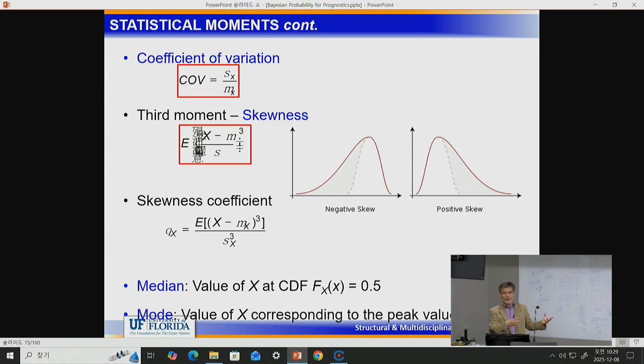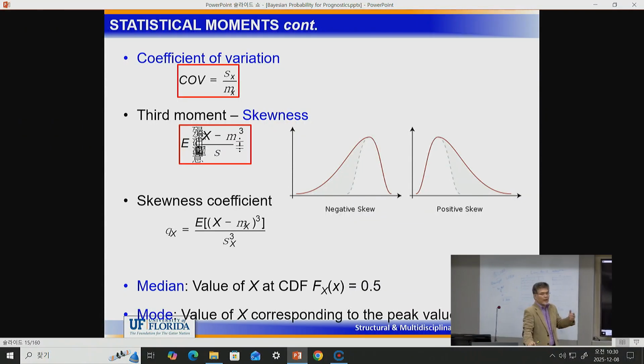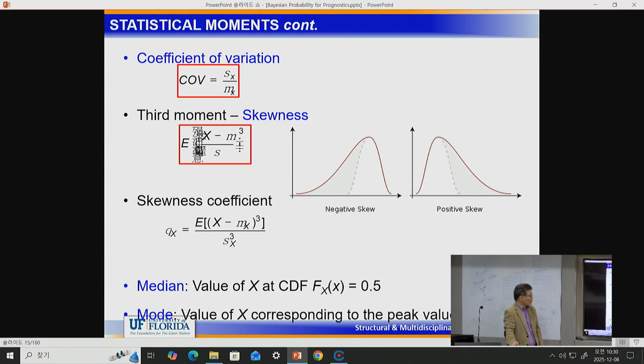then it's highly likely the samples or data may come from that particular distribution, right? So this we call statistical tolerancing, meaning unfortunately in school we have a distribution, normal, log normal, and we generate the samples. In practice, it's opposite. You have a sample, and then you need to infer, estimate what distribution it comes from, and what the parameters of the distribution are. So these moments are important to compare, both for finding the source of the distribution and for how to estimate them.